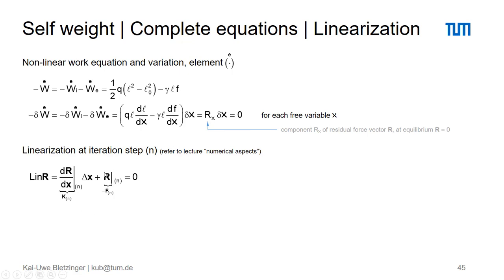We have the residual force vector at step 1. We linearize this residual force vector by again taking the derivative with respect to the three variables. That will receive the stiffness matrix and multiply that with the still unknown modification of geometry, which we can solve in this linear equation. And then we repeat that for every step which is necessary until we reach the goal where the residual force vector and all its components are 0.